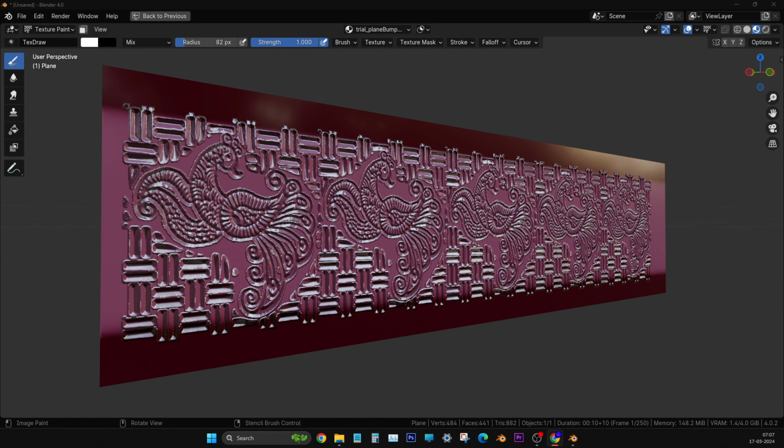Right. Go to Add, Mesh, Plane. Now go to top view. Front view is okay. Now go to the Rotate option in the left side toolbox, the red color X-axis.